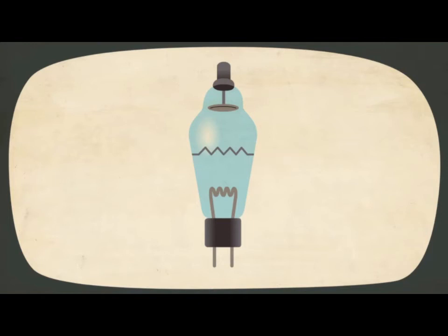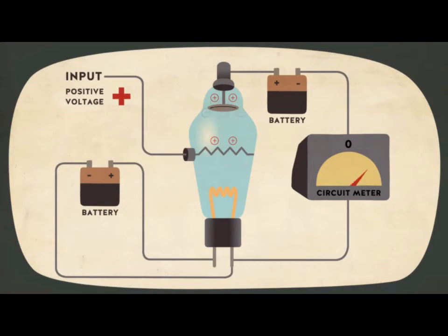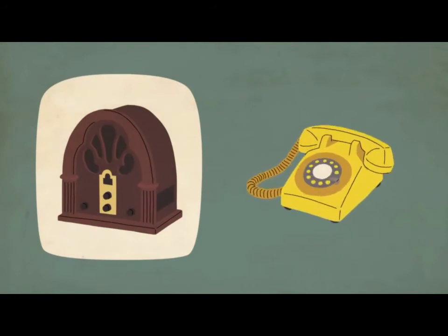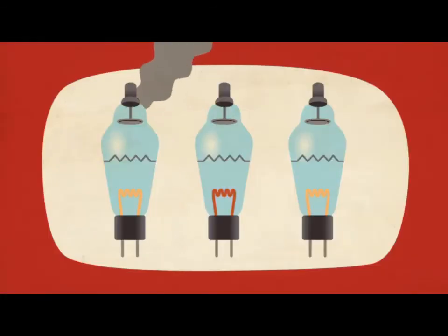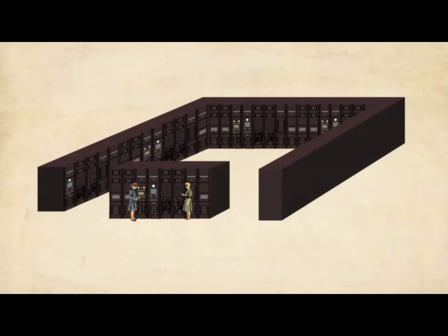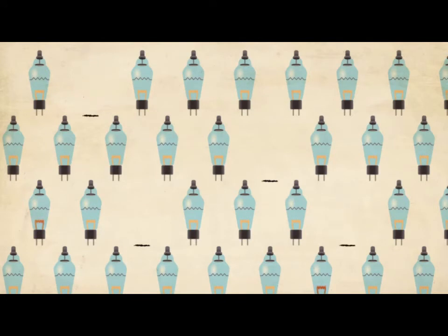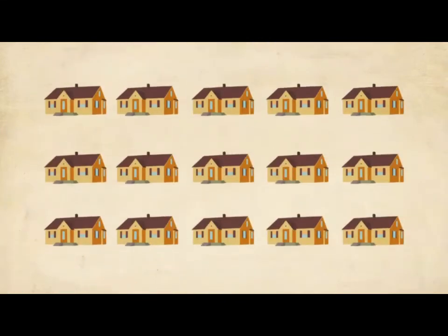This is a wire screen between the cathode and anode through which electrons could pass. Varying its voltage makes it either repel or attract the electrons emitted by the cathode, thus enabling fast current switching. The ability to amplify signals also made the triode crucial for radio and long-distance communication. But despite these advancements, vacuum tubes were unreliable and bulky. With 18,000 triodes, ENIAC was nearly the size of a tennis court and weighed 30 tons. Tubes failed every other day, and in 1 hour, it consumed the amount of electricity used by 15 homes in a day. The solution was the transistor.